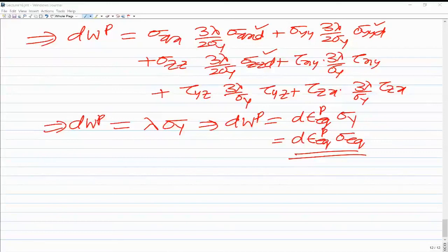In case of isoparametric formulation, we need not use the local coordinate. We can use the global xy coordinate and do the formulation. That is still straightforward. The expressions are going to be the same for the isoparametric natural coordinate formulation.